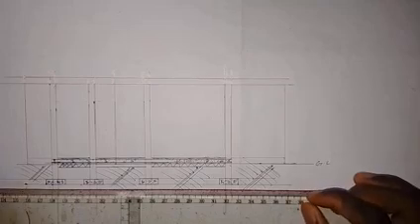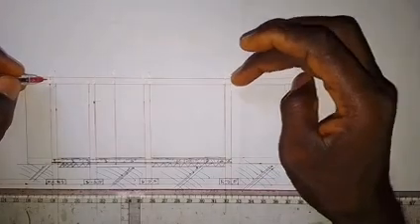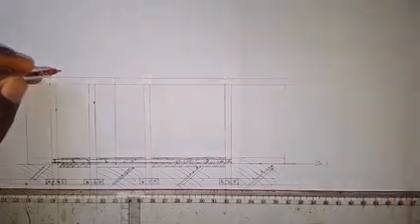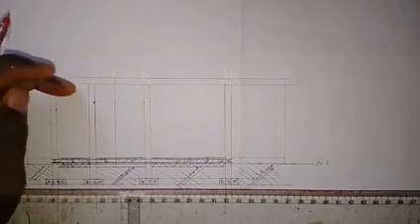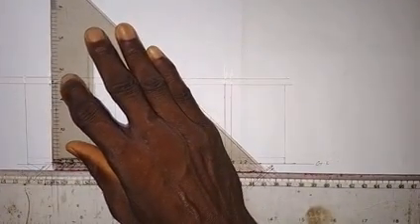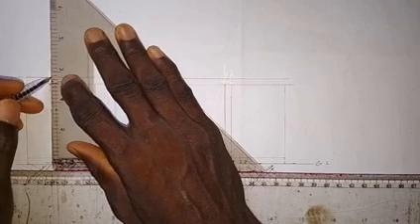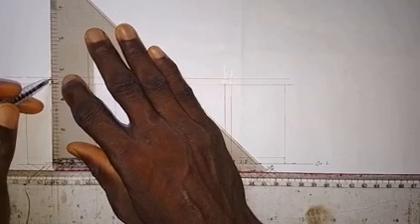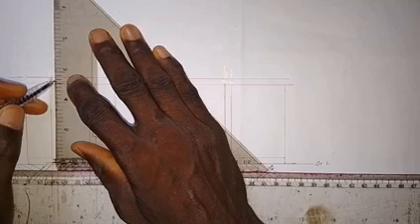Next thing I'm going to do here is to create the wall plate on this wall, and I also create a wall plate here. Then I'm going to fix the ceiling joist, as we are given this ceiling joist here. So I'm going to fix the ceiling joist around here. So let's go and see. For the wall plate that I want to draw, I will just come here, and I'm not going to take a measurement for that. So I will just draw a vertical line here and move away a little bit.